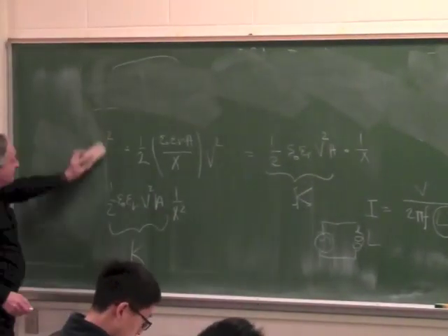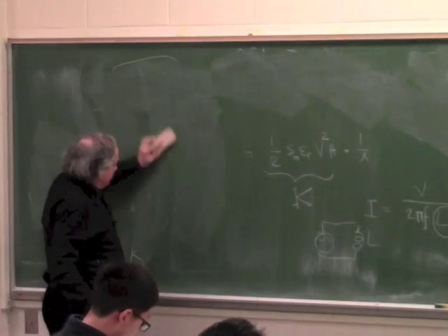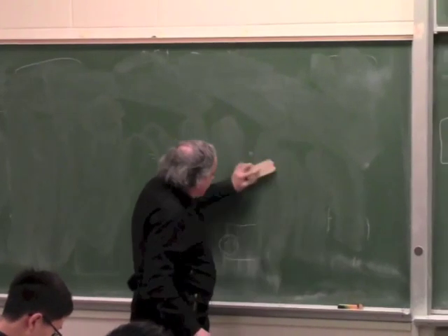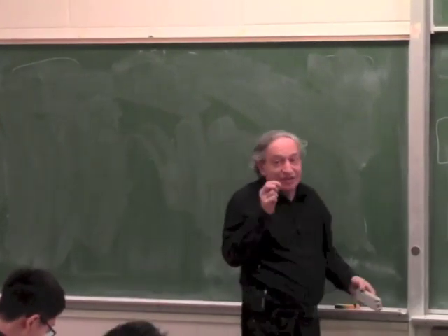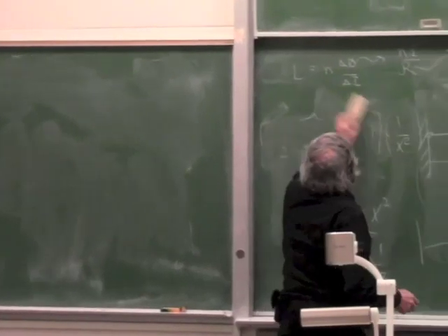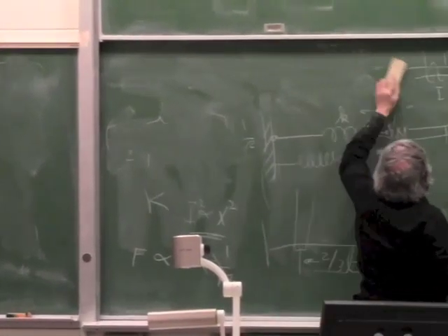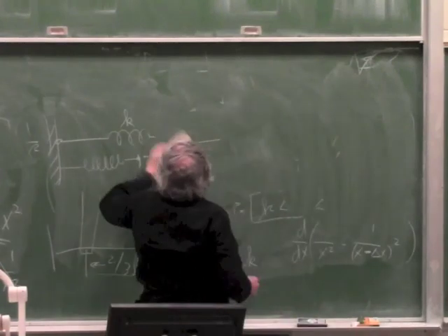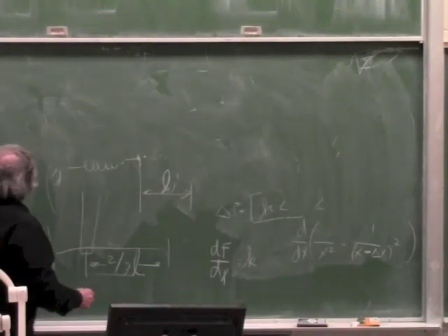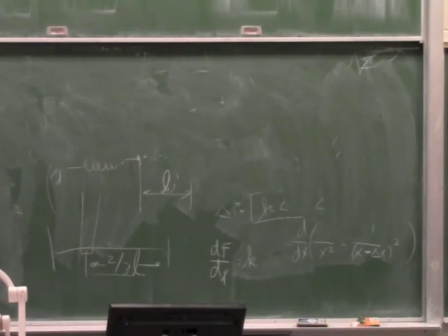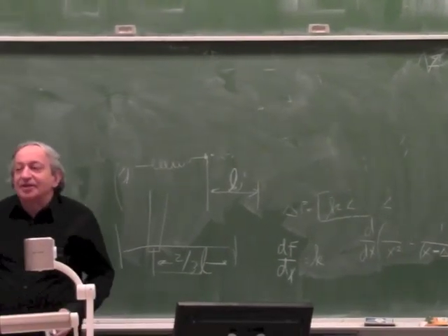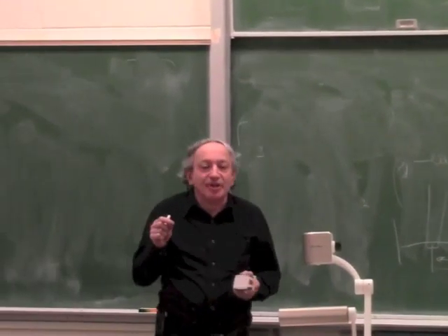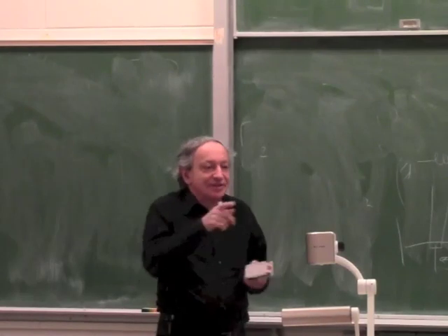I also mentioned in the last lecture that a very common actuator today is actually electrostatic, although it can have very small forces. The reason the electrostatic actuator became common is that it's very good for MEMS, because you don't have to make coils. And when the gap is very small and the actuator is very small, the electrostatic forces are comparable to electromagnetic forces.